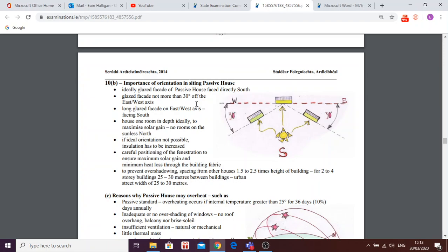If you want to put a kitchen and a sitting room separate, then that can't happen most likely, because you probably want to have them both south facing. If you want to have 3 bedrooms and only want a single story, unless you're going to make your house extremely long, then that's maybe not possible either. Okay, so sometimes that is not possible, but in those situations, all you have to do to get it up to the passive house standard is to increase your insulation.